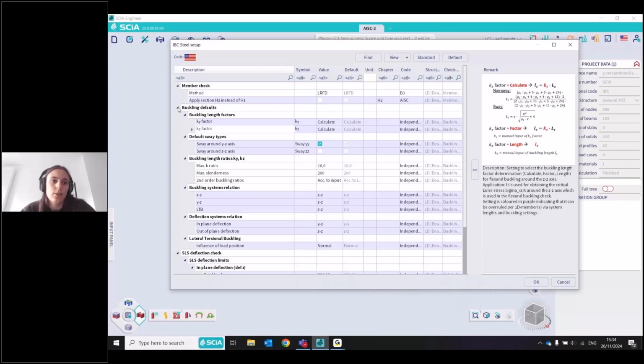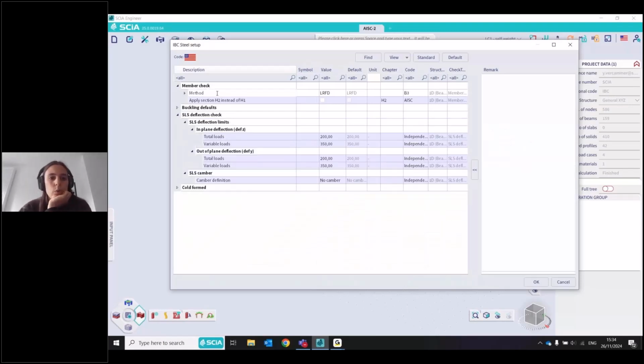The most important setting of all is the method to choose for the steel design. And this one should just match the one that you've chosen for your combination. If you're doing allowable stress design with the combinations for LRFD, then you will greatly over dimension your structure because you will not allow for much stress, and you will put high safety factors on your loads. Well, this would be the better way to do the error because the building won't collapse, but still it will be a high cost for no reason.